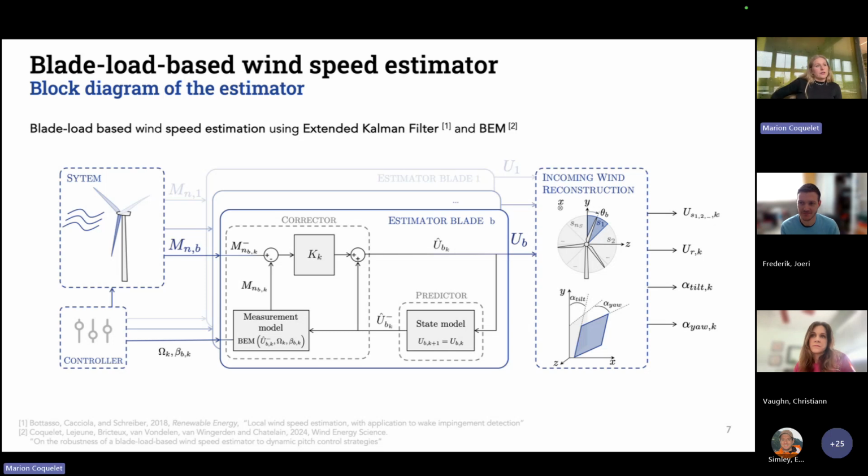Yeah, that's a really good question. Once I had the question, why don't you have the exact same measurements for the same input wind speeds if you use the same polars for your BEM and your LES? Why do you have a difference in the models? That's intrinsic to how you compute. You might have the same polars, but you don't compute the blade loads equally when you use a BEM or the LES, because of all the sampling of the wind speeds.